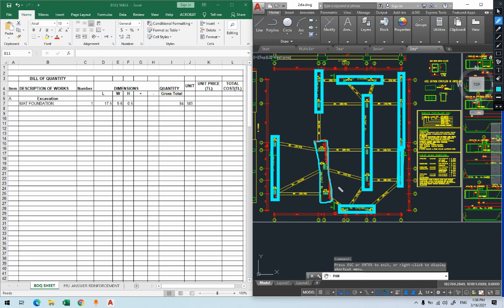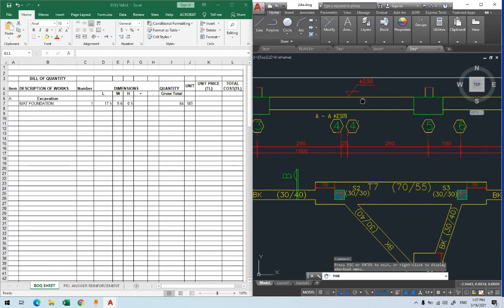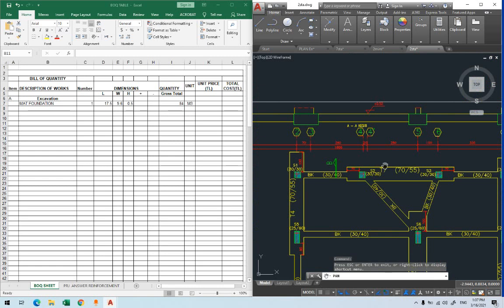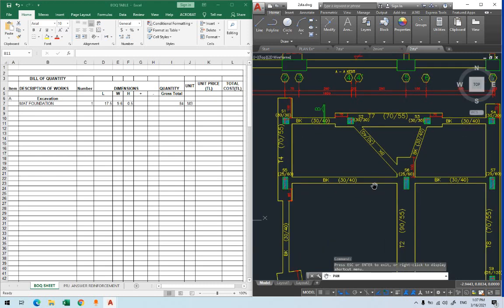In some places, you will see that they make some miscalculation for this value here. Let me tell you, this value here, the level of the top of the foundation, that the ground beams will not be on the natural ground. So sometimes you have to be careful. Whatever the plan is, you're going to go through it. But do not always say that since we have ground beams, yes, those will sit on the ground. You have to check to see if they haven't made any mistakes in the calculation. Normally, we do it this way: the ground beam will sit on the ground.